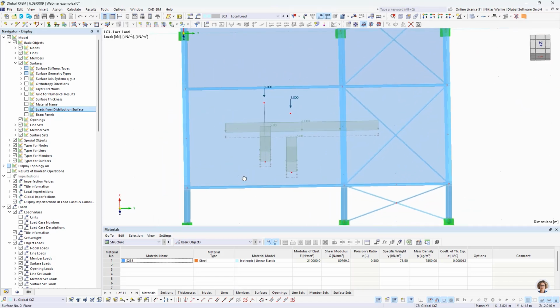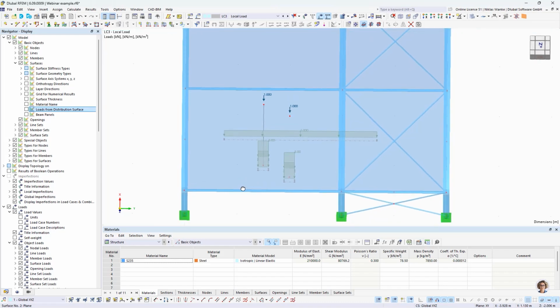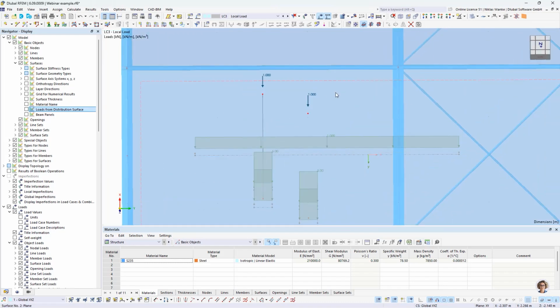Normally, the equilibrium is considered. This means, for example, this load is located at 2/3 of the span of this roof. So it would mean that 2/3 of the load would go to the right rafter, and 1/3 of the load would go to the left rafter.